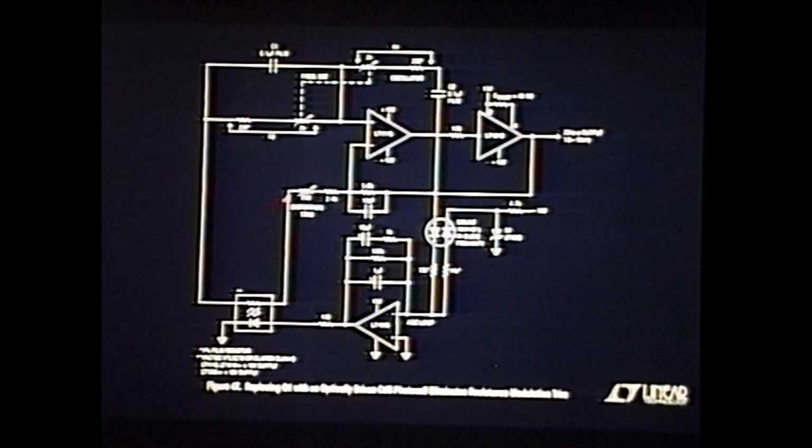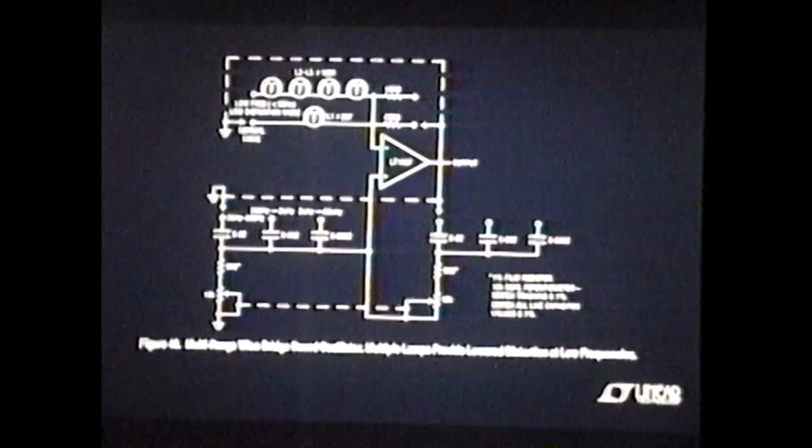Here's the hole. I think I know what the problem is. What's the fix? The fix is I've got to get rid of this common mode swing here. Well, how in the name of God am I going to do that if I'm driving a bridge around the input? The way to do it is to unbolt this bridge from ground here, which unfortunately isn't in the diagram, and drive this end of the bridge out of phase from the amplifier. That's hard to see in this diagram. Let's go back to the simpler one. The only way I can think of to fix this problem.